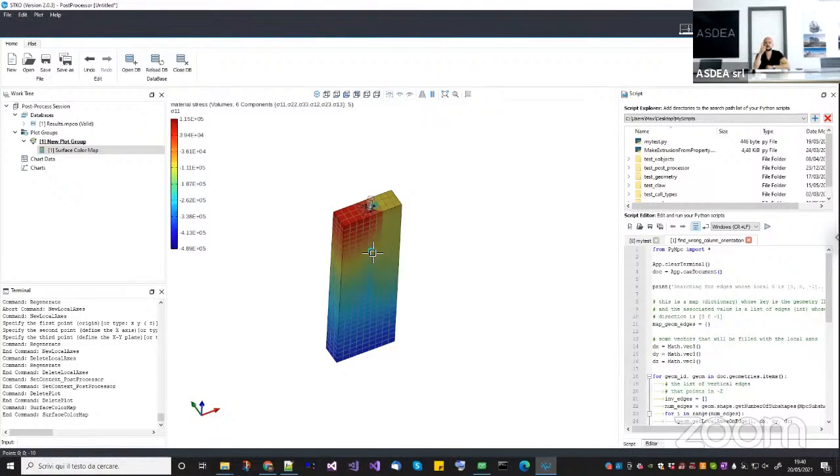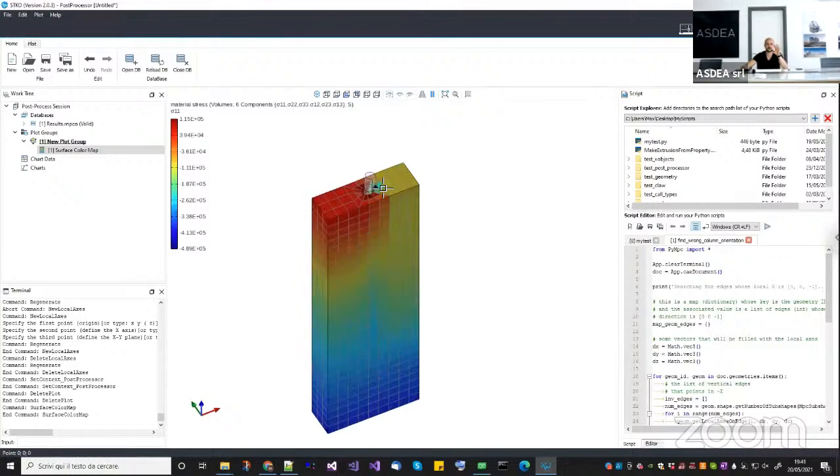And there is also Dennis here. Dennis implemented this element, and I helped him just a little bit. The nice thing about this contact element is that it is always convergent, because it uses a particular kind of integration scheme that makes the analysis stepwise linear. What you will see is that I set up the contact parameters and the time steps in such a way that this model converges, but you will see that contact is very, very unstable.